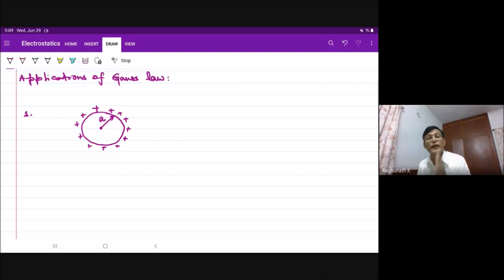Because it is a regular surface always in these cases, we will know the expression for the area of that surface, knowing the amount of flux passing through it. We can determine the flux density at any point on that imaginary surface drawn through the point of interest. We will know it in direction as well as magnitude, divided by epsilon of the medium in which we are looking at the field expression. We will get the electric field intensity.